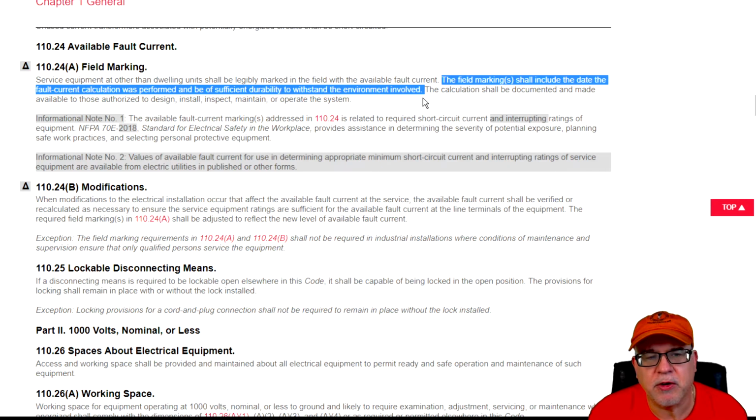Again, many people underestimate this concept. I'm putting the service equipment outside, but I'm putting a label on it that's going to be subjected to temperature changes, moisture potentially, humidity. So I have to make sure that label is going to endure. And so it's real important to think about the label. I've been to jobs where it's just been an inkjet, okay, and it's just not going to work. Over time, the ink's going to fade on it. All those things are based on the environment where it's located. So it's important to make sure that it's designed for that.